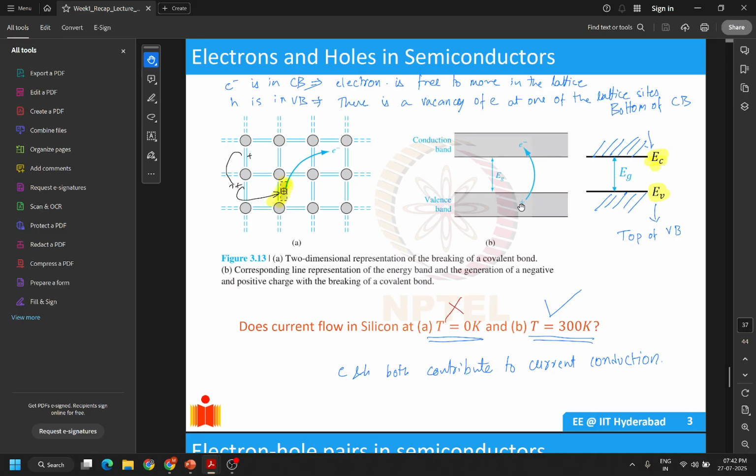So although the vacancy is attached to the nucleus of the atoms, it behaves like an electron. We call this vacancy a hole, and we consider it to be like an electron but with the opposite charge, because it is in the inverted parabolic region.